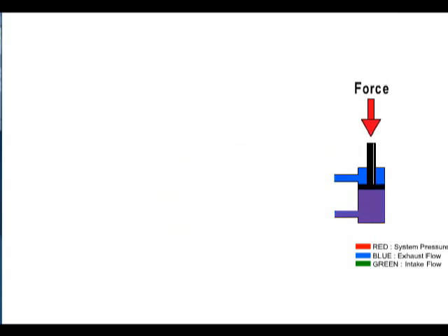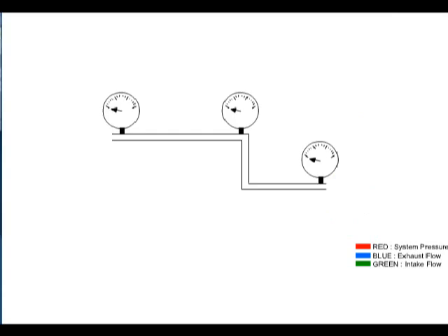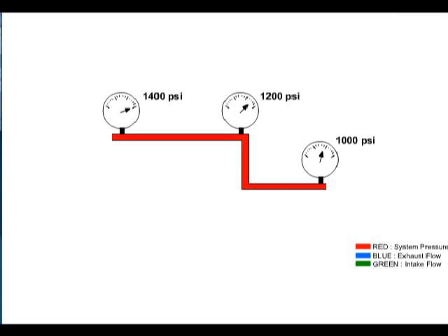This resistance to flow is load-induced from the actuator and also generated as the fluid is passed through the various conductors and components. All points of resistance, such as long runs of pipe, elbows, and various components, are accumulative in series and contribute to total system pressure.